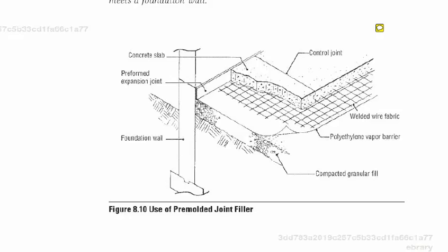Concrete is almost like a living being. When it gets hot, it expands. When it gets cold, it contracts. You have to incorporate joints. You're going to put basic preformed joints into concrete along edges against walls so that there's room, especially for concrete to expand, that it has a cushion. Otherwise, if it has a solid object, the forces of it being pushed against the solid object will cause cracking.